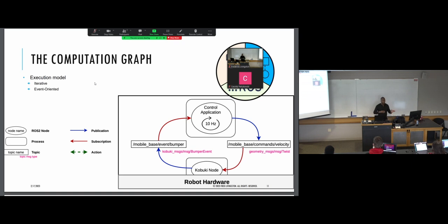So today we're going to work on waypoint navigation, where you could breadcrumb. Once you have a map of your environment, you could give it just like a GPS kind of thing. You could say, go to this waypoint, go to this waypoint. And you could get through a track just by going through waypoint navigation. But it's going to be subscribing to your odometry and your laser to figure out where it is, localization and mapping. And then once you have a map of your environment, you can lay out grid points and then be able to navigate. So everything is publishing and subscribing to different sensors or algorithms to make something work here.